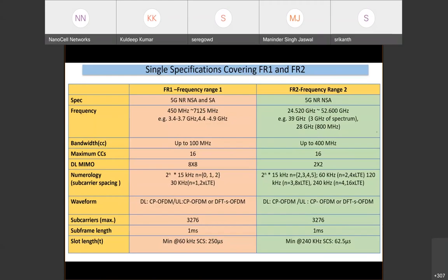There was a question about spectral efficiency differences between LTE and 5G-NR. I thought that was interesting. It's a slightly more nuanced question, and in fact, there are results presented by 3GPP in their evaluation. One of the main tenets of 5G is that we are allowed to do large bandwidth channels. Even if you take FR1, which is the fair region to compare with LTE, LTE by design is limited to 20 megahertz, whereas in our case, we can go 100 megahertz.